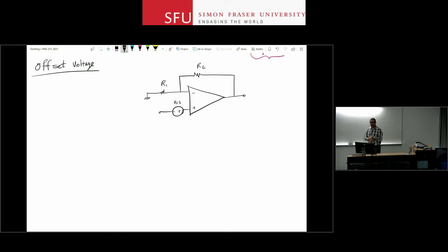But the non-inverting input, sometimes you ground it, sometimes you put it in series with the voltage source at the input, and it's just easier to have the offset in there as well. The inverting input is where you apply the feedback from the output. Usually the circuit around that input node is more complicated, and you just don't want to add complexity by adding a voltage source there. So this is how you model it, and this is really it about the offset voltage.